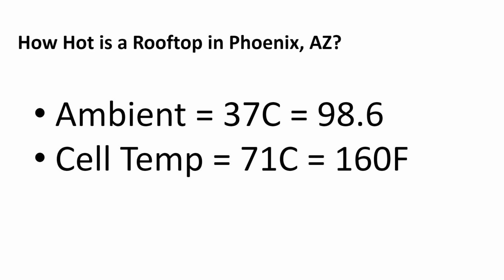75C or even a 60C temperature rating. Generally your solar cable is going to have a 90C temperature rating. So you don't want to just use cable that you can buy at Home Depot all willy-nilly for wiring up your outdoor roof-mounted solar array. You need to make sure that your boxes, your terminals, your cables have a high enough temperature rating.